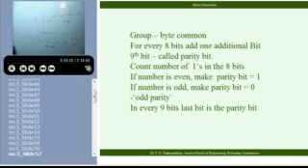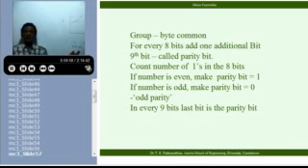I have started off the signal. I have done a sampling. I have done a quantization. At the beginning itself, I am saying that I am prepared to accept a certain error in my transmission. That is, I have done a round off, consciously and intentionally. I am sending only this, so consciously I have introduced a certain amount of error in rounding off. But at the other end, any value I get between 1.5 and 2.5, I interpret as 2.